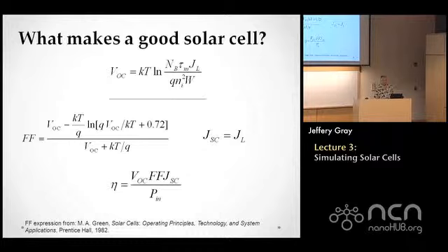The fill factor expression here is actually quite exact. You can actually calculate the fill factor exactly. It turns out to be a transcendental equation. And I thought about deriving that for you today, but that would have taken the rest of the time probably. You can check out this reference, and he talks about how that comes up. But this is quite good all the way down for band gaps down to about 0.2 of a volt. So for all intents and purposes, this form for the fill factor, ignoring series resistance anyway, is quite exact.